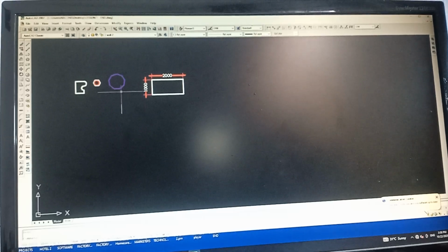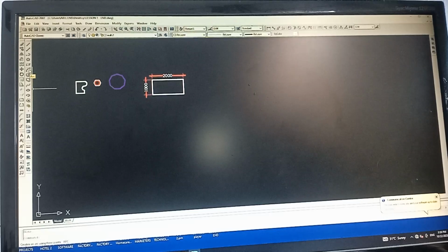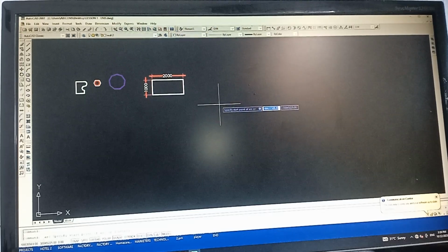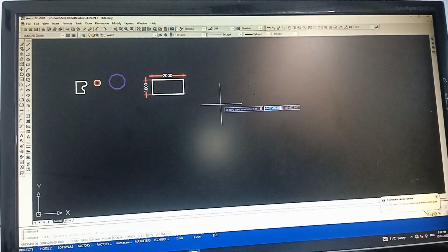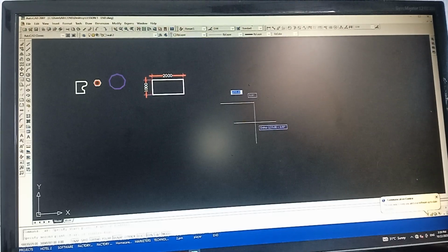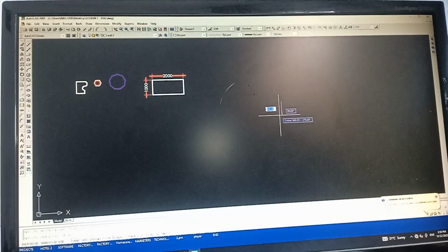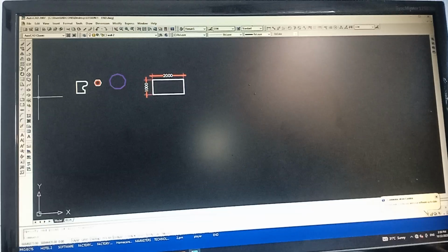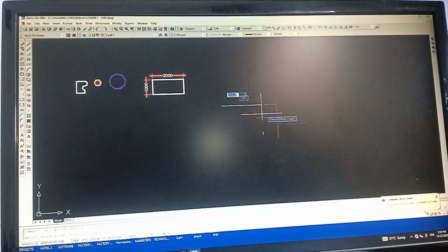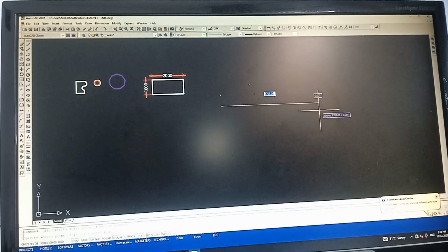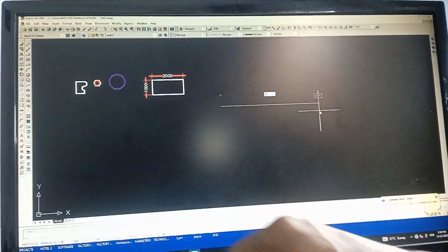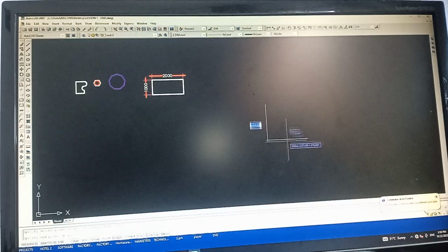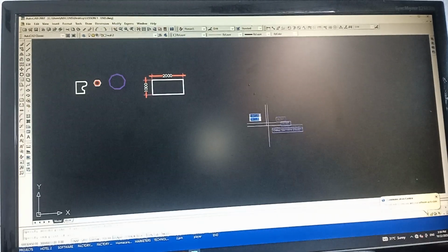Okay, at this point we move to our next item today, which is the arc. How do you work with your arc? We pick the arc tool and specify our first position. When you specify your second position, the arc will come out. But you don't just do it off-handed like that. Let's say we pick our first position. Remember, an arc is the same thing as the diameter of a circle, a half circle, a semicircle. So how do you pick your diameter? Let's say the arc is 3,000. We press enter. That will give us what? Can you now see your position here?